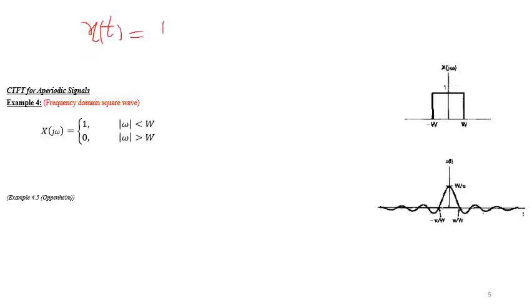integration. You understand, in case of Fourier transform, we scale the inverse Fourier transform, right? If you recall, in case of the Fourier series, the scaling was 1 by T. So in case of Fourier series, we had the analysis equation: integration over T of x of t times e power minus j k omega naught t dt.